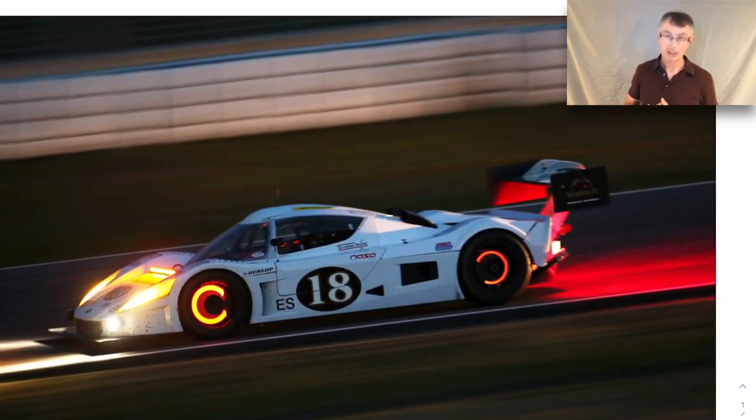So you have to be careful of that, because if it heats up too much, you can actually cause your brake fluid to boil, and when that happens, your brakes become very squishy, and you lose braking ability. So you have to make sure you cool down the brakes. They'll sometimes do some venting on it and such, just to make sure it doesn't overheat.